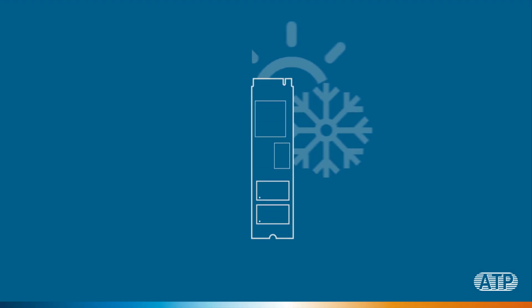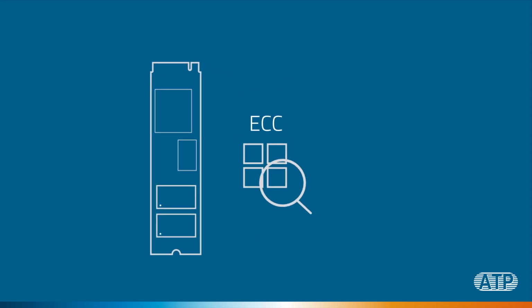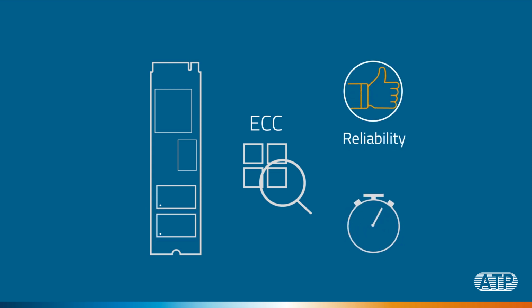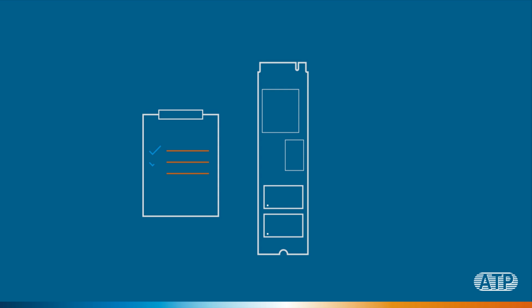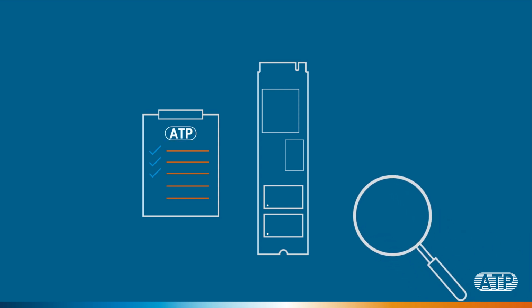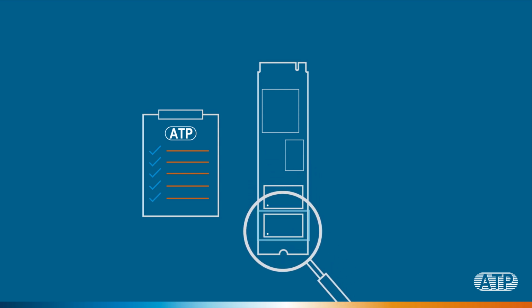RDT helps us make sure that our product can endure extreme operating conditions. Based on predetermined ECC criteria, we use stress accelerants such as temperature and power to help us identify weak, unusable blocks and to improve drive reliability and endurance. Many module houses perform reliability tests according to their standards. At ATP, we believe in uncompromising quality that meets and even goes beyond market standards.